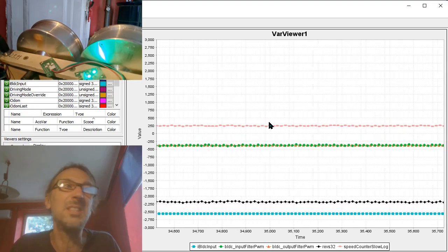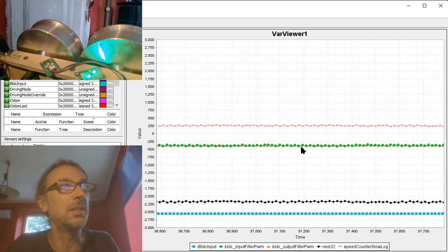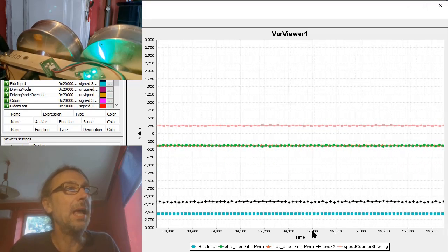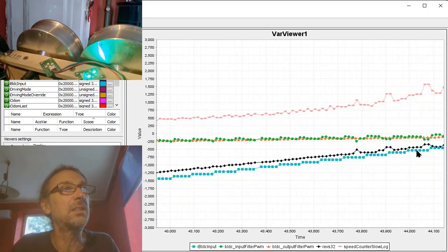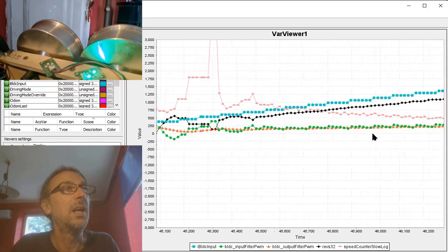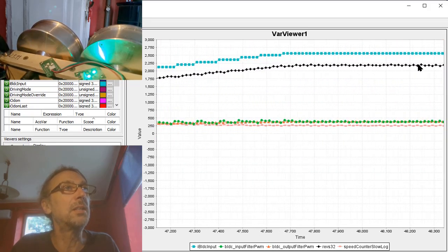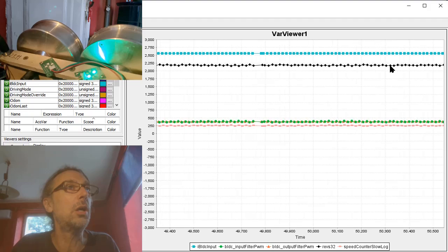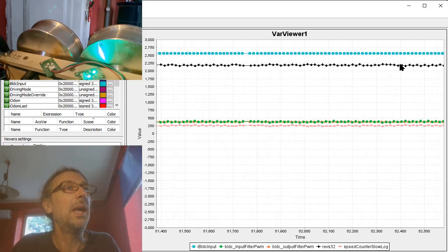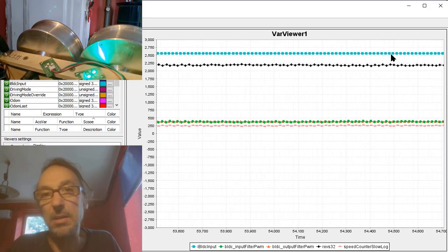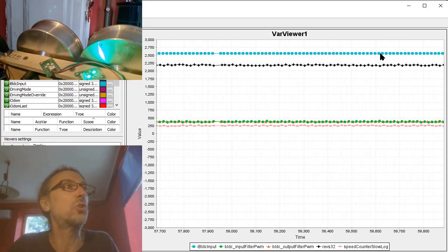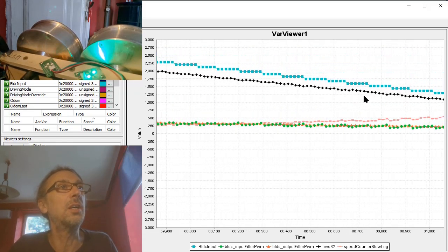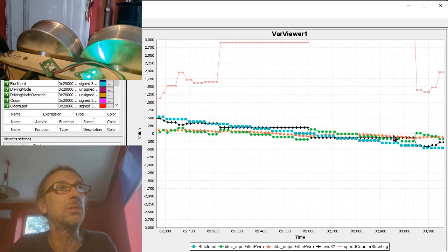So DeepSeek did not really get it perfect. What's more interesting here is the black. That's the speed, really. And here at very low speed, I have to disable the low pass now. Yeah, quite nice speed. And here, again I don't know why, because that's what the PID should achieve, and it's always a bit too slow.